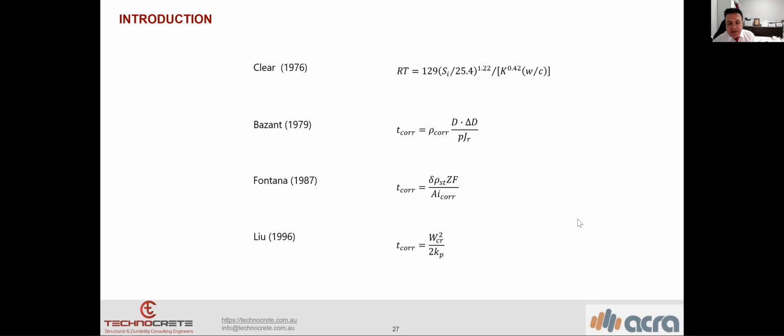flexible, and laminate is for shear strength. Strengthening is more suitable than wrap. I mean, if it's for shear strengthening, we use carbon fiber laminate. But in this case study, which I showed you, we couldn't use it because the carbon fiber laminate has to be locked into the concrete itself. Then we couldn't use the carbon fiber laminate. And the other product is the carbon fiber rod, which you saw.